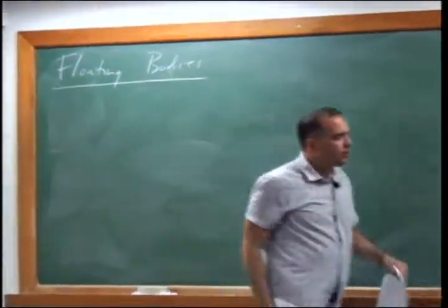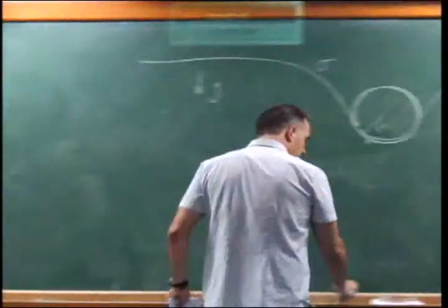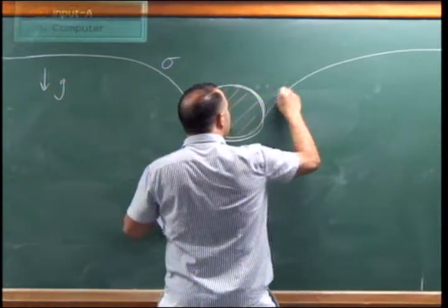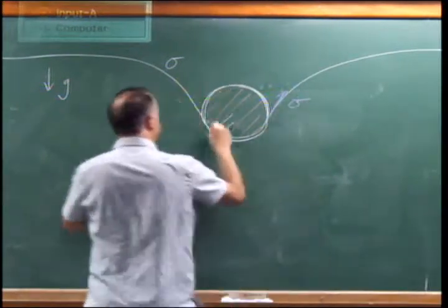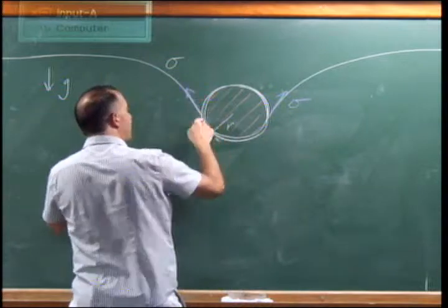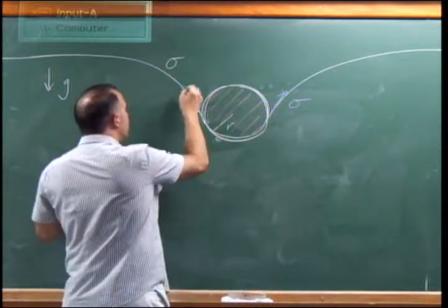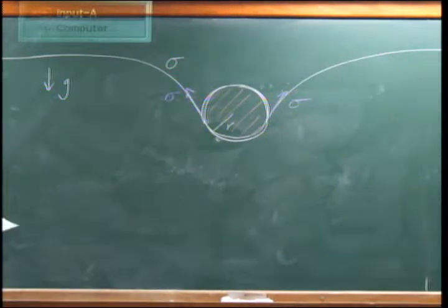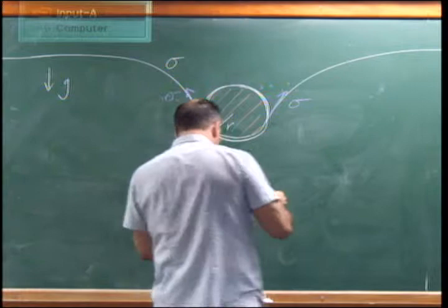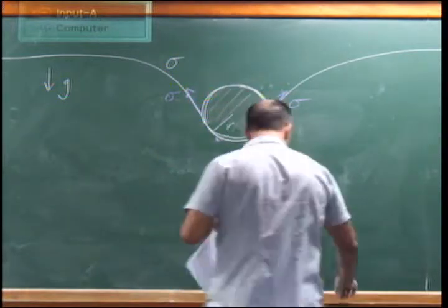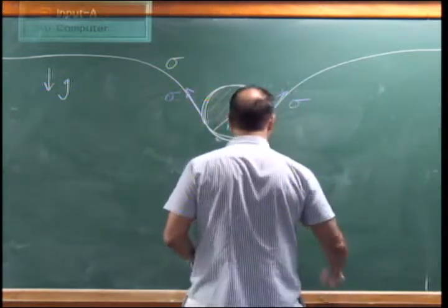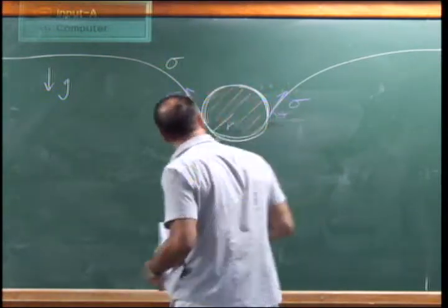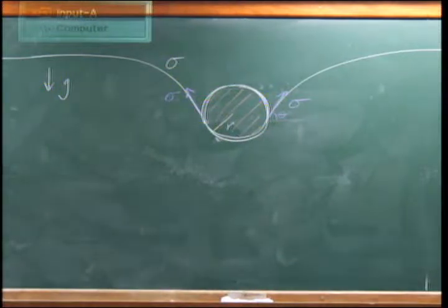So we know there are two basic forces that are going to act on this. One is interfacial tension, and we know immediately what that's going to be. It's basically going to depend on this angle, right? We know the magnitude of this is going to be surface tension, so it's only going to depend on the local geometry of the interface. So we can call this angle, say, theta. And that, of course, can be related to the contact angle.